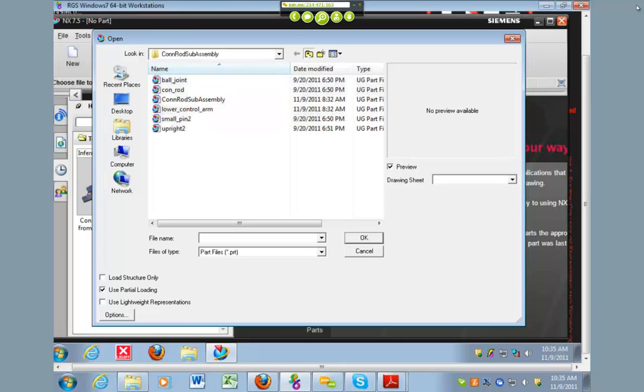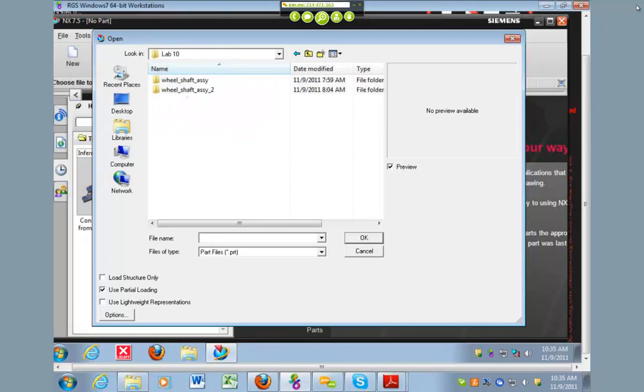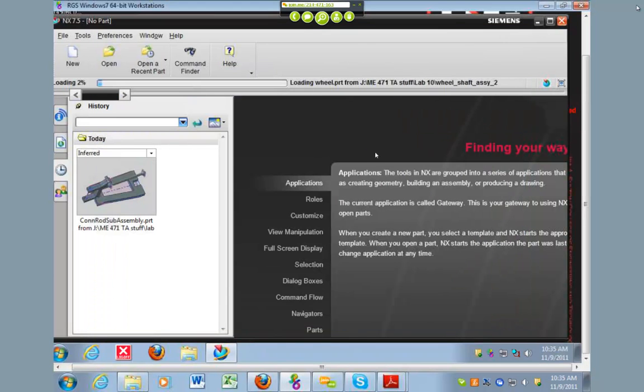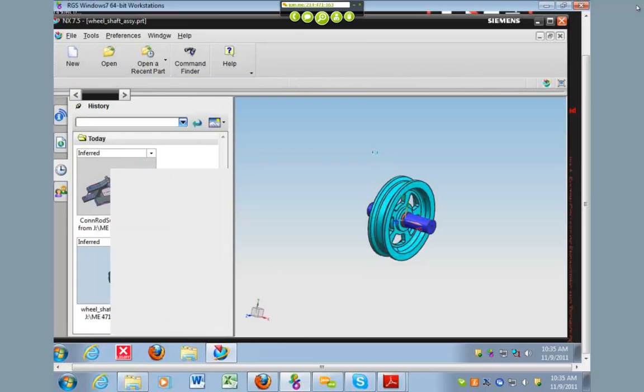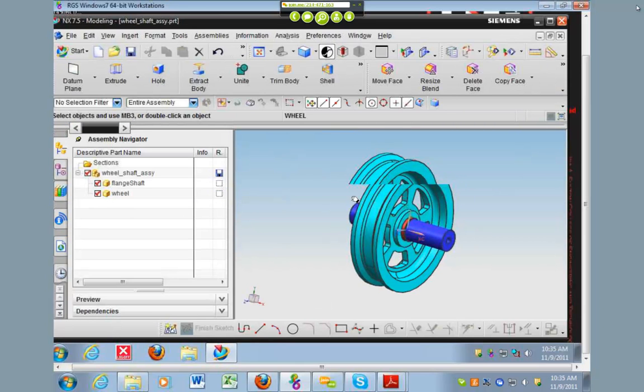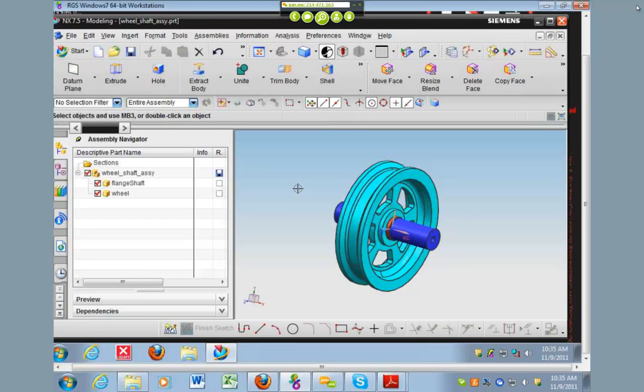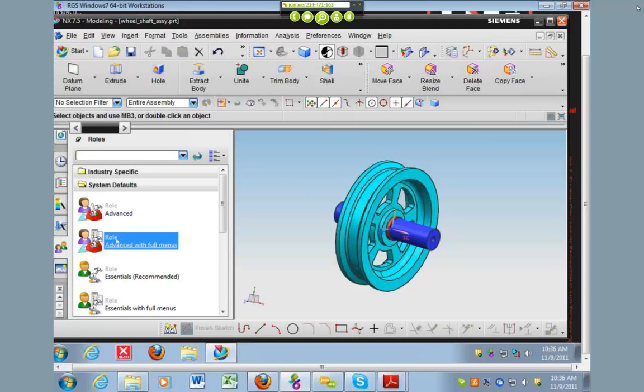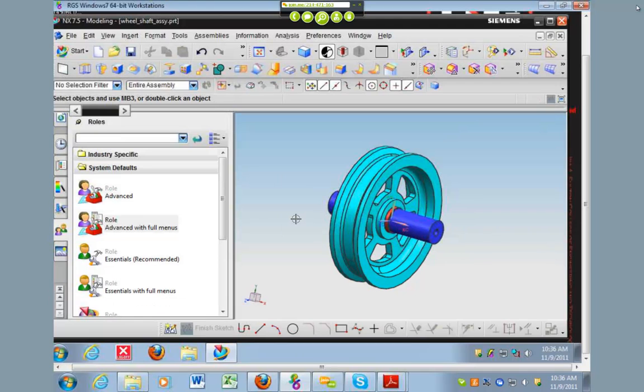Now, in meshing one part, you don't have to worry about connections. You just constrain it and put loads on it, and you're good. However, in this one, you have multiple parts. So you have to associate the two parts through some type of interface. In NX, there are three ways to do that. There's a surface-to-surface contact, a gluing contact, and then 1D rigids.